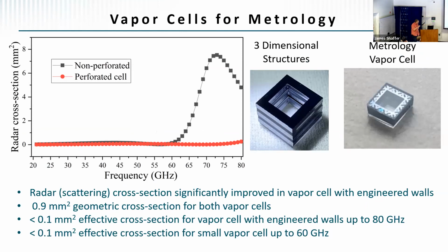We actually stick these things in an anechoic chamber and measure against the horn. We also look at the correlations between the cells, sticking them closer and farther apart to see when they start to essentially talk to each other.